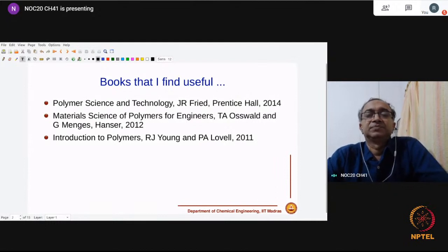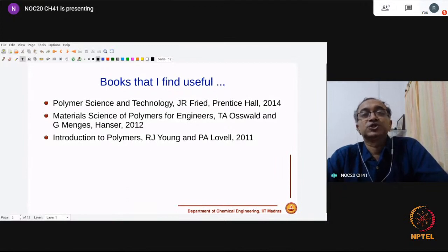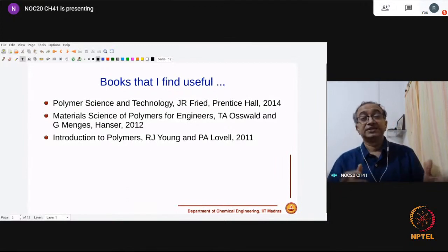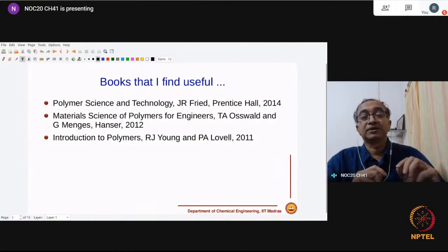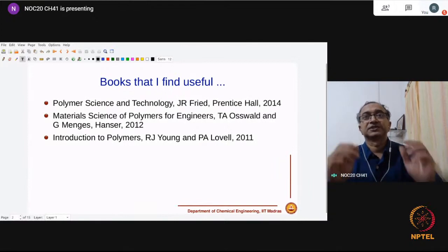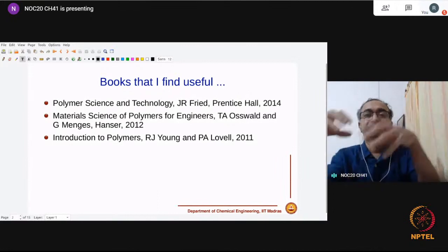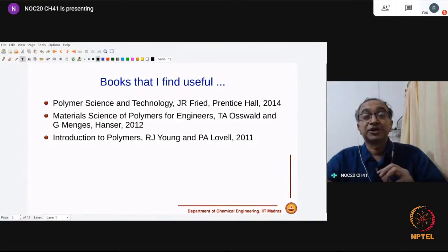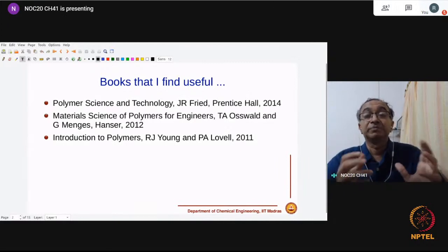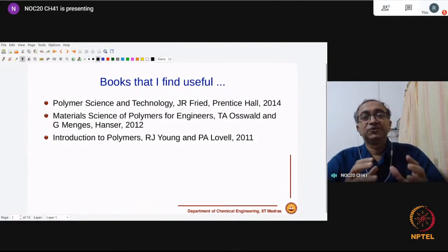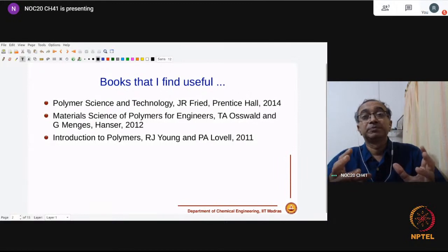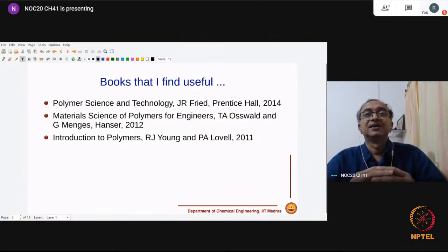Compatibilization is needed because we rarely use a single polymer. We will most often use a blend where we mix two polymers, or quite often we may have a composite where we put a glass fiber or a calcium carbonate filler or carbon fiber or Kevlar fiber in a polymer matrix. Given that we are putting two materials in a mixture, the interface can be the weakest link. So the material can fail at the interface.